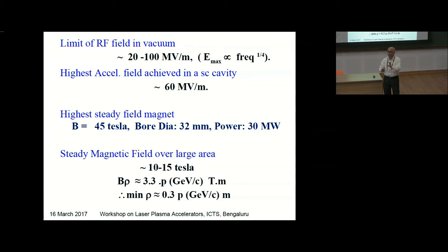Normally in a metal, these electrons are flowing, and there is a work function, which is the potential barrier. Now, when you put a very strong field, this potential barrier comes down. So the electrons just come out of it. This is what field emission is. So field emission takes place, and once the electrons start coming out, they multiply inside, and they drain out all your power. All the electric field that you have set up will be drained by these low energy electrons. And so you will not be able to power your beam anymore. So that's the limitation.